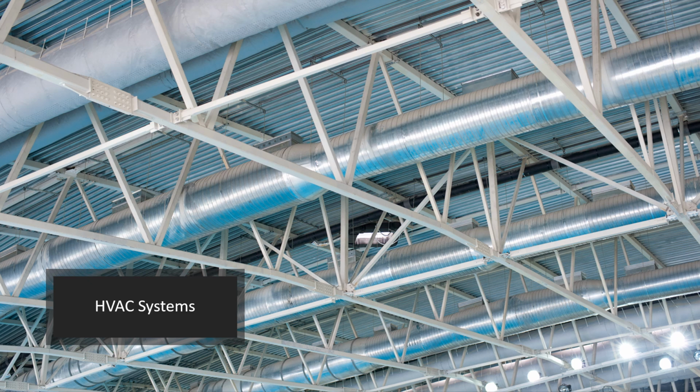And due to the large and sometimes demanding environment, HVAC systems in sports facilities must be designed for durability and easy maintenance. Regular inspections and cleaning of filters, coils, and ducts are essential to maintain optimal function. You also want to look at energy efficient design strategies. So in some climates, using natural ventilation strategies like windows and vents can reduce reliance on mechanical HVAC systems. And solar energy systems or geothermal heating and cooling can be integrated to support HVAC systems and reduce energy use.